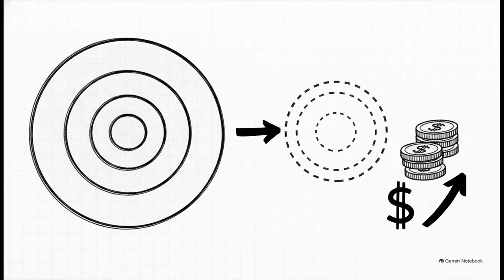This is exactly where you step in as the principal engineer. By deliberately adding the maximum material condition modifier, the M inside a circle, to the tolerance value, you completely flip the economics of this part. You unlock bonus tolerance. As the machined hole departs from its maximum material condition, meaning as the hole physically gets larger, the positional tolerance zone is allowed to grow by that exact same amount. This guarantees the parts will still perfectly assemble, but you just save the manufacturing floor immense time, money, and scrapped parts by giving them dynamic breathing room. It's a total game changer.